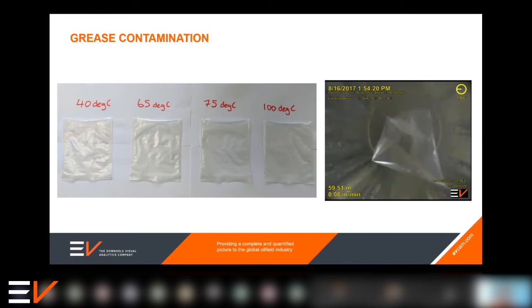I think that the biggest issue that we face with cameras is maintaining that optically clear environment. It's the one thing that we have to rely on. And really, the first few hundred feet inside the well is probably our most problematic, especially on wireline interventions where there could be a lot of grease used to help lubricate and maintain pressure.